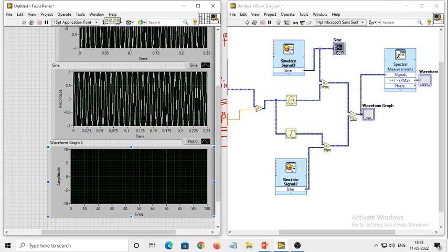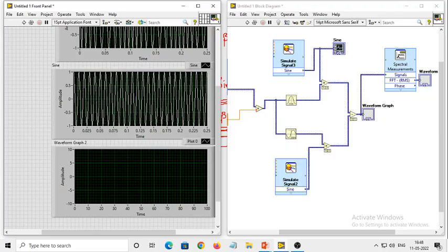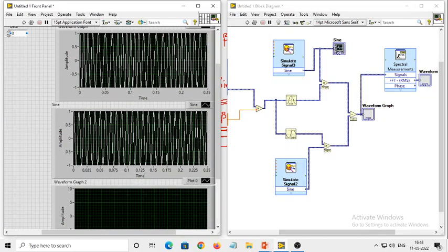The spectrum of FM looks something like this: you will have a carrier frequency and multiple sideband frequencies. Those multiple sideband frequencies depend upon the beta value. One thumb rule is you need to get more than 2 side frequencies whenever you give beta greater than 1.